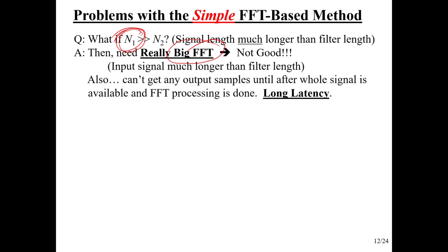But that's not the worst of it. The worst of it is that you can't get any output samples until you've collected the entire signal. That's the biggest problem with this simple FFT-based method. You have to bring the whole signal in. So if you're in a real-time application, you get the first sample, the second sample, you have to wait.